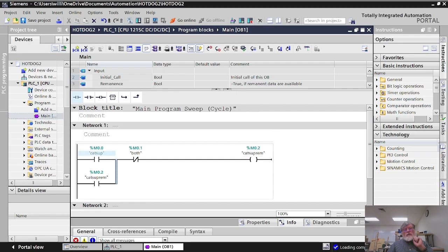And this is when you push this button, until you push this button, this sets, this turns on, and it also comes back here, so you can let go of this and it'll still run. So you can tie this in, and it's kind of like a tie down, it ties the logic so that you can go this way or you can go this way. Either way works to get this bit to turn on.